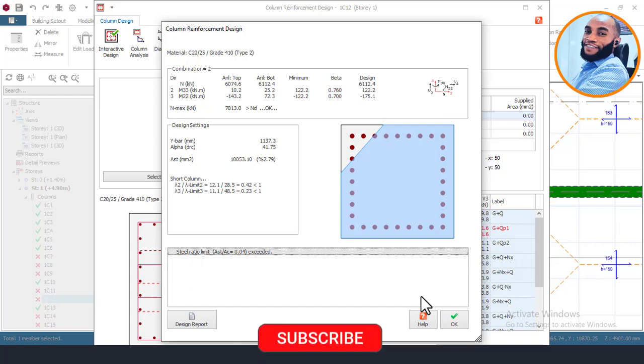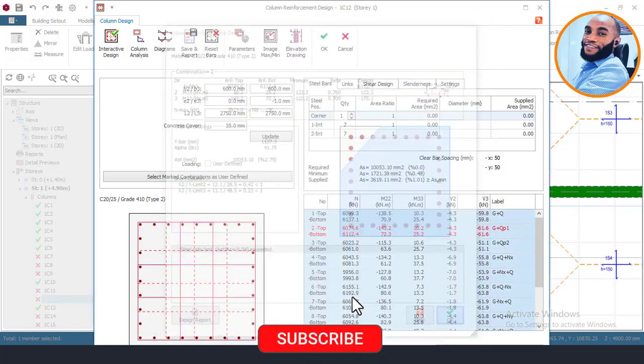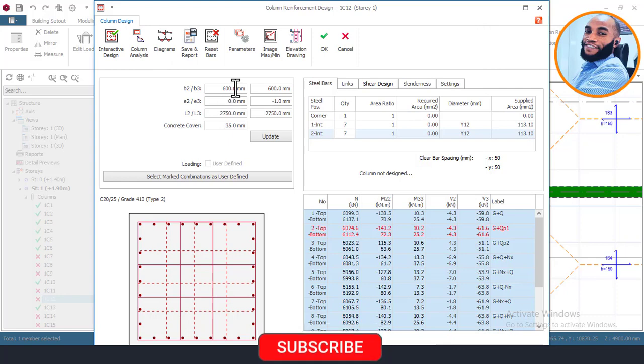Okay, so I'll click OK because it's failing, and then I'll come here and increase the size of the column. Now let's increase the size of the column to 650, and also here to 650.